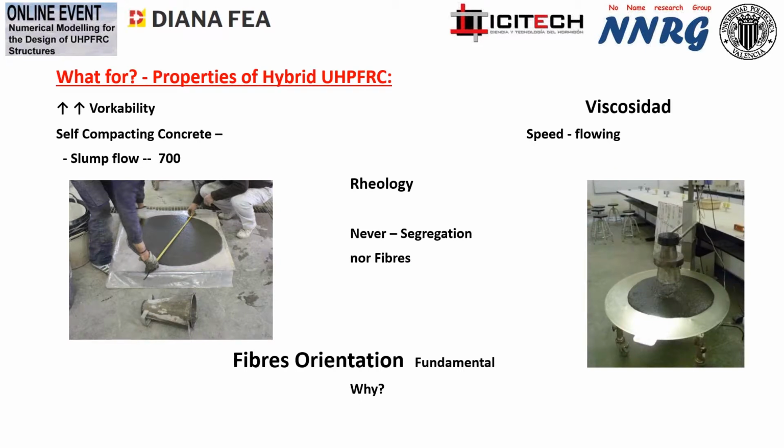Okay, I talk on workability. Workability will produce fibers orientation, and this is a point we will need to work with. And you must understand how your concrete is moving, because considering this movement, considering the presence of rebars, the presence of other elements in the way of the concrete, you will have some orientation. But as you have lots of fibers, fibers will always be oriented in all directions. You can have a preferential orientation, and you need to understand that.